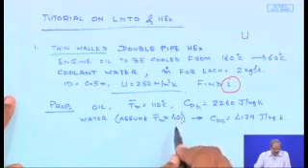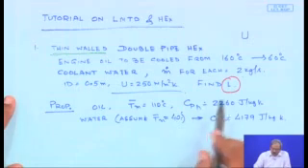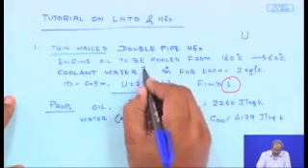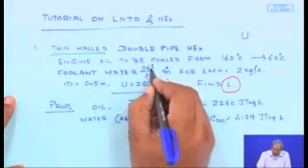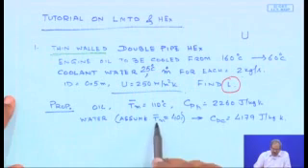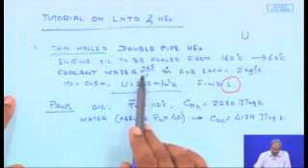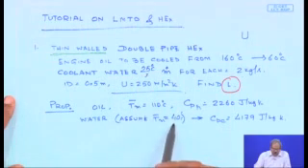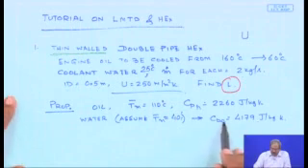You would see towards the end, and the coolant water is at 25 degrees centigrade. So obviously the outlet temperature is going to be more than 25. So I assume some Tm, which can later be checked with the actual value that you are going to get. So this is going to give me a value of Cp for the cold water as 4179.